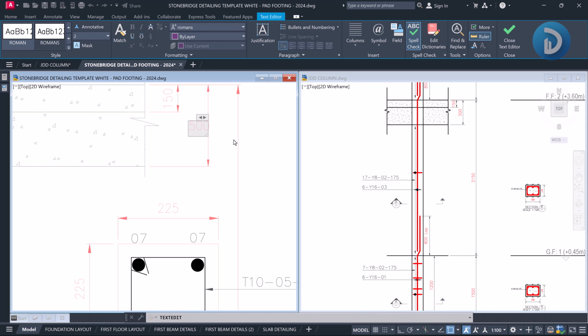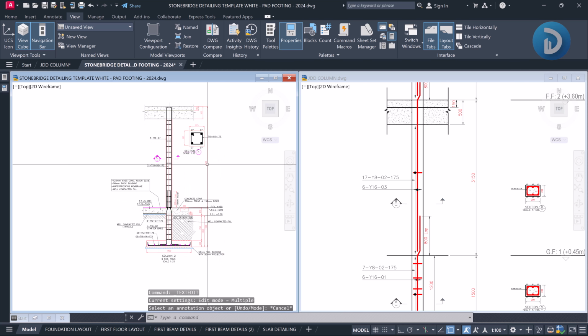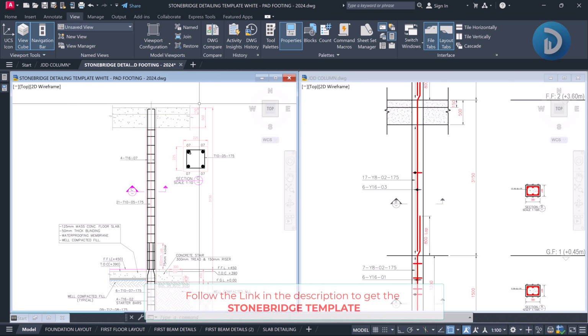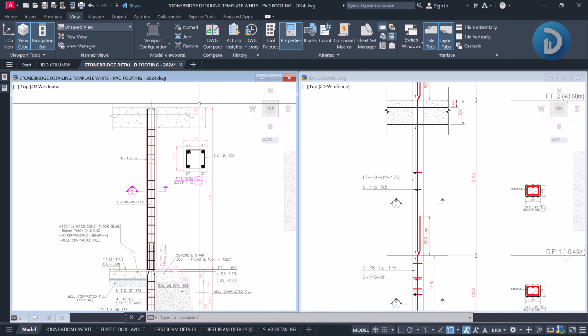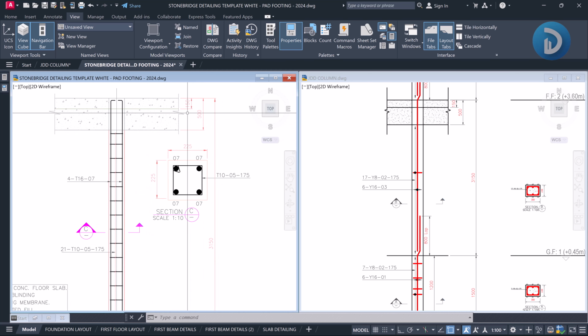Do not forget that the most important thing in detailing is being able to communicate effectively to your artisans on site. There is never a time where the artisans or the iron benders will take out a tape or a meter rule and try to measure your drawing to scale, right? What they will look at is your dimension. So what is important is you give them the appropriate information that is required. So this will be edited to 500 millimeter, and this will be at 150 millimeter.